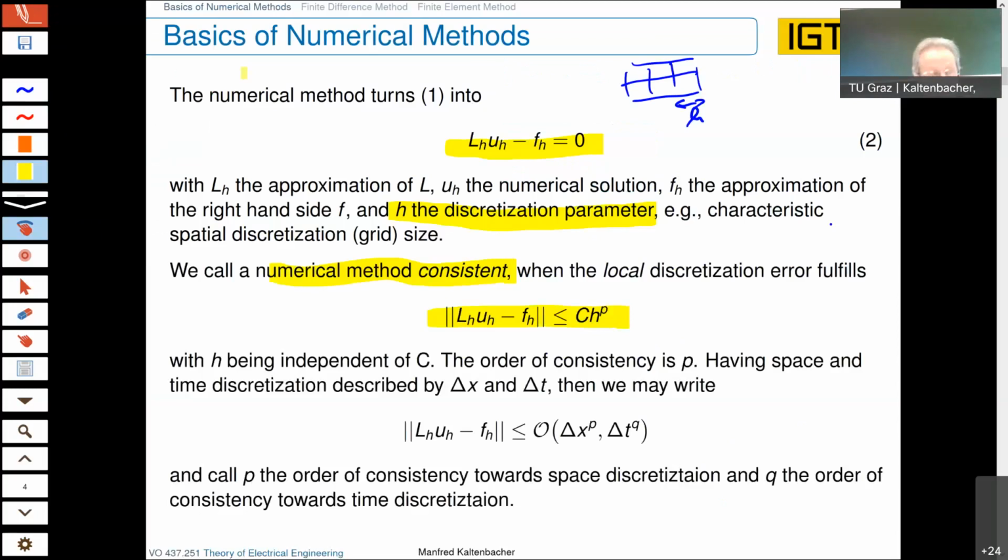Okay, and you see, when you have your discrete operator multiplied, which will be our system matrix at the end. After the discretization, we get out of the Laplace operator a system matrix multiplied with the unknowns, U_h, the unknowns at all the nodes. These are the nodes, and at all these nodes we want to have our physical quantity.